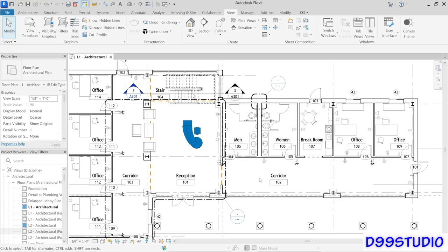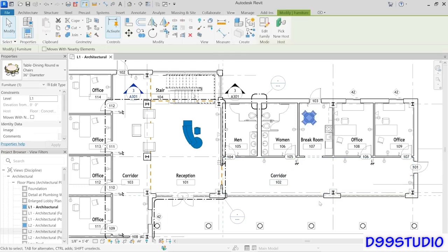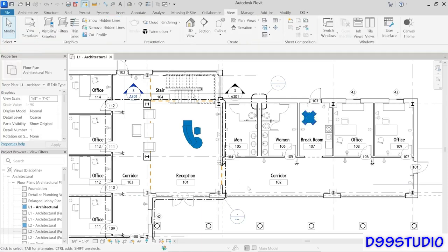Now, the cool thing about doing it this way rather than right-clicking and selecting it individually is, if you go to any other item now and decide that it is also by others, it will immediately take on the characteristics established in the filter. So it's a much more powerful and consistent and easy to maintain approach. Even though it takes more effort to set up the filter in the first place, I think it's completely worth it. So I hope that you'll agree that using display filters is a superior approach to these kinds of issues, and I encourage you to explore them further.